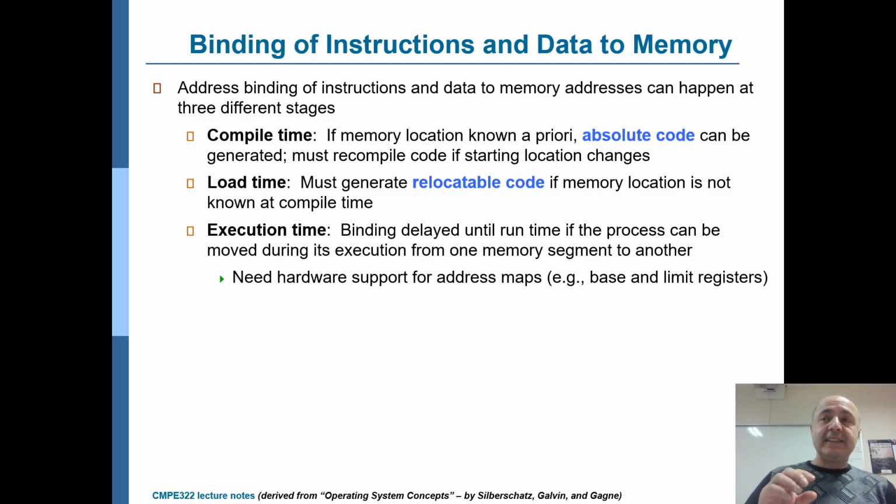So it knows exactly where the program starts. Therefore, it also knows where the specific variables and functions will be. Note that if you do something like this, and later you need to move the functions or variables around, you have to go back to the source code, make modifications, recompile, and then install the recompiled binary once again.